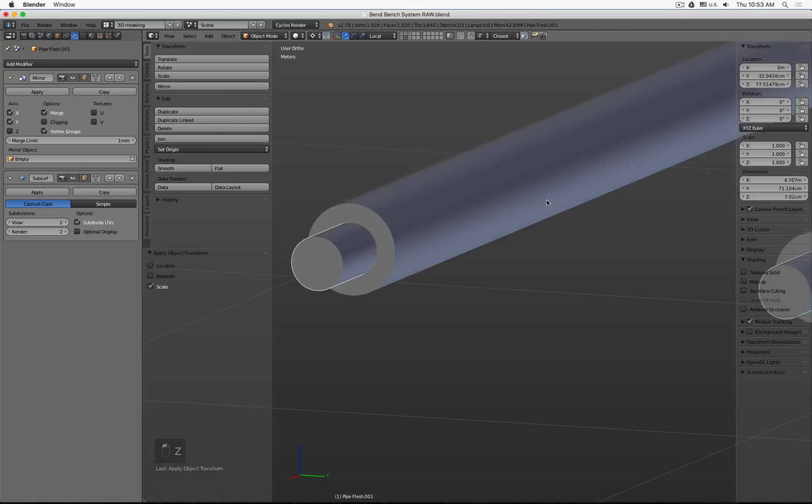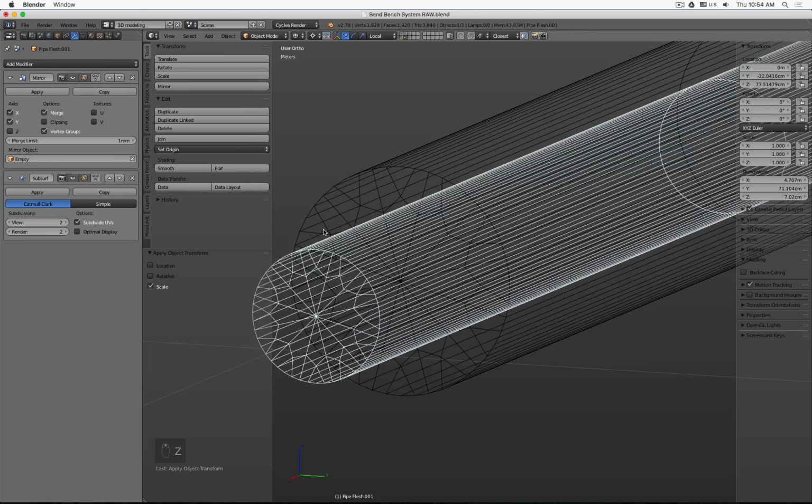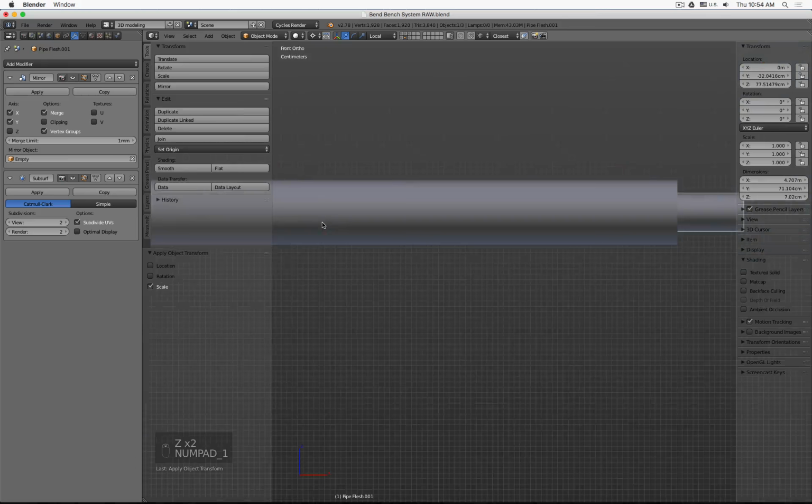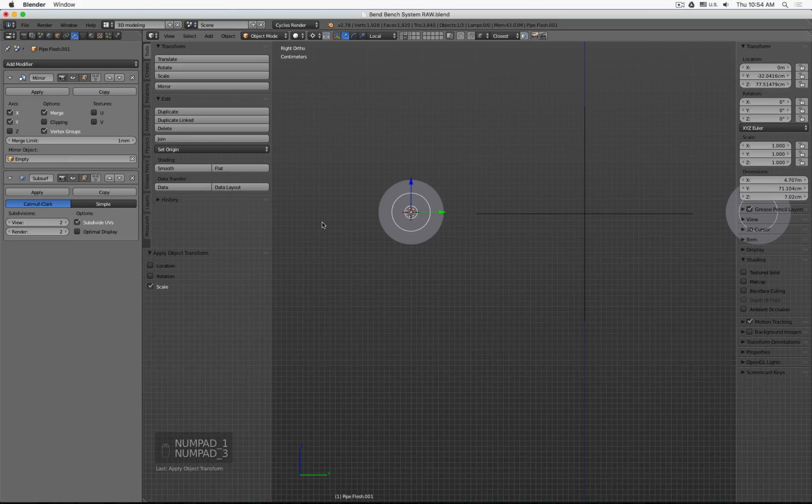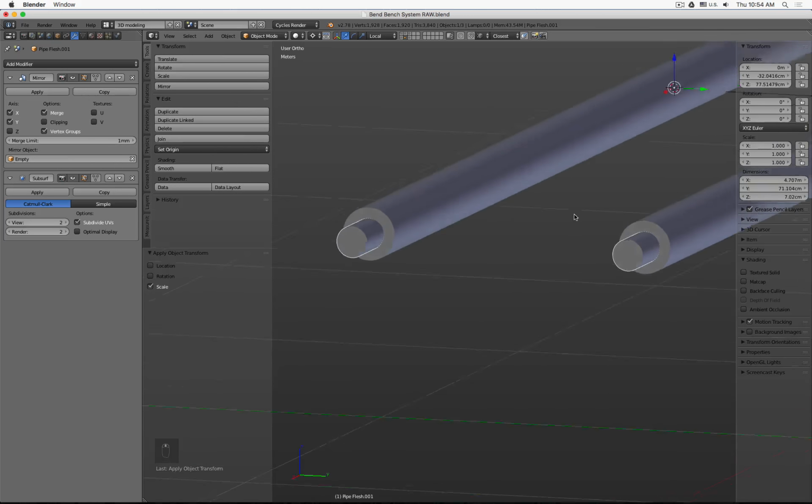Okay. Again, the main reason why I did this in Fusion is that we only have fully smooth or blocky. And in all other programs that use a subdivision, you see we just add more faces to make it nice and round. So because in Fusion it's super smooth and precise, that's the reason why for the sizing I set this to 6, adjust the number, and then later bring it back. And this way I know I'm pretty close to what I need when I bring the data over to Fusion.